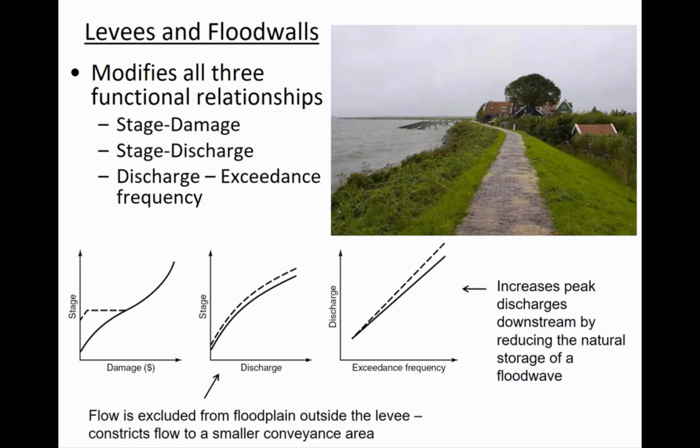Does anybody have any questions about the levee and flood wall? Yeah, Austin? Would it be more beneficial to match the slope of the side of your channel and extend it up to the curve of the levee, as opposed to just putting in a flood wall that restricts the width? That way you still have your width, but you still have that barrier.